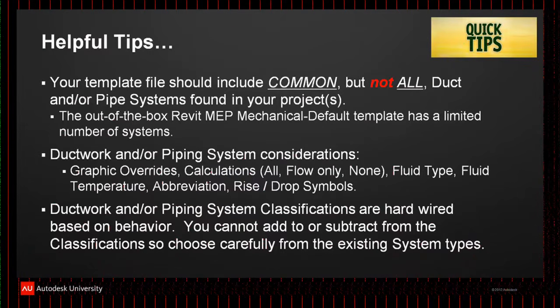The other reason is that when you start listing everything in here, how many people do multiple different types of projects that don't focus solely on hospitals? You're doing schools, you're doing hospitals. Is a school system going to have a medical vacuum, or a grade school going to have a medical vacuum in it? Is it going to have medical air in it? Then why do you want to be bothered seeing that in a drop-down? That's one of the reasons we say teach your people how to put piping in, and that's one of the things we're going to talk about. There's a couple of catches there that you have to understand.